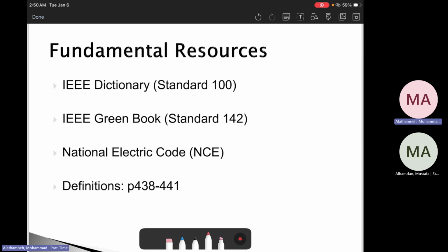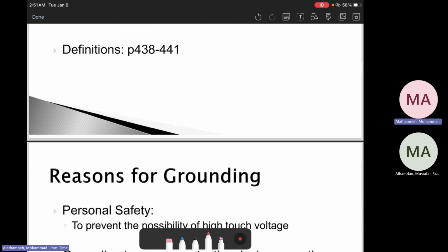So if you want to be a real professional, rely on definitions and standard evidence. Don't say, I think it is like this, or I think it's like that. That's not the situation. You should take some measurements, look at the problem, analyze it, and look at the evidence, looking for grounding and customer-end problems. After that, look at these standards, make sure you are familiar with their definitions, then see if the measured values comply with the standards or contradict them. That's what we need to worry about.